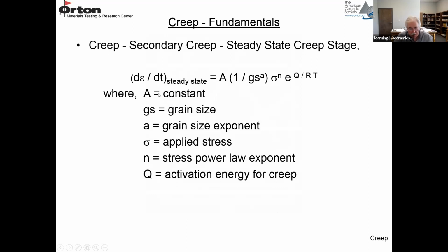So where most of the modeling takes place is in the secondary creep region. That's the region that's been studied extensively. That's the steady state region. And an equation has been developed to describe creep in that region.